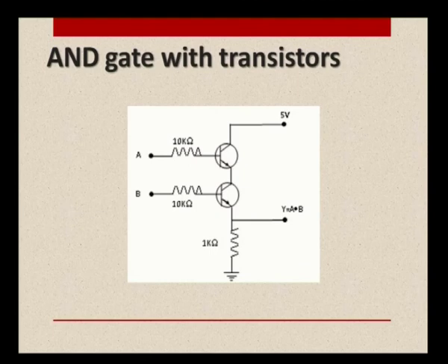With that knowledge, we can have a look at the circuits, and the operations are very simple because we have learnt already how transistors are used as switches. Now, the AND gate is designed using only transistors in this manner. Now, we will take up for our discussion the combinational gates like the NOR and NAND gates.